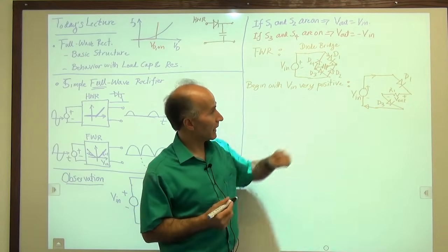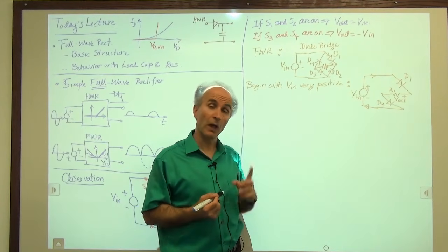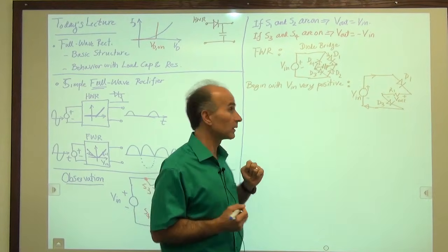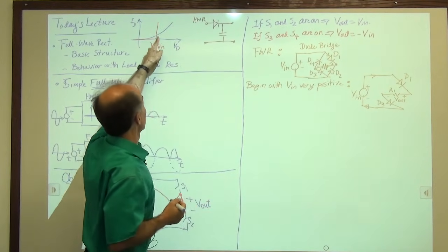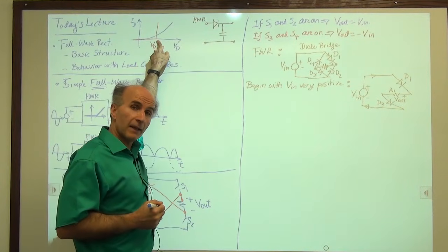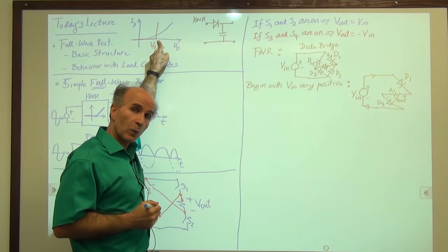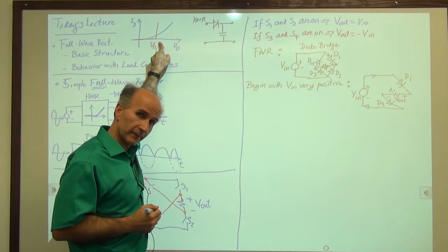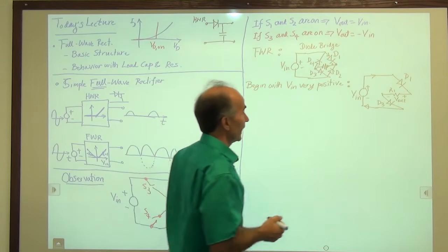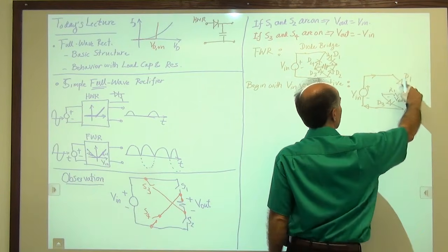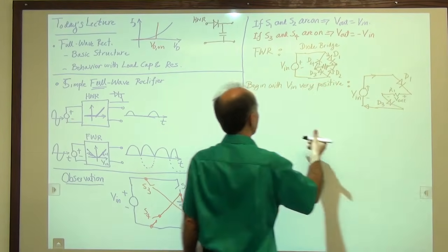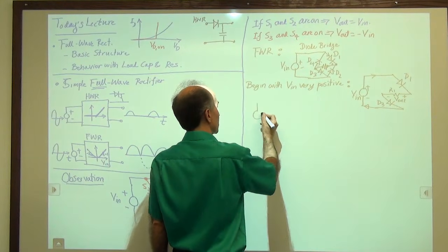Okay, can I simplify that circuit? Well, I know that the diodes are on, and I will use the constant voltage model if you remember. So I will replace every diode that is on with a battery of voltage VD on. And then I won't draw it like this. This is somewhat silly. Why don't we just draw it like a straight branch? So we'll draw it like this.